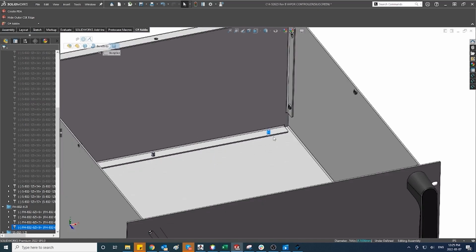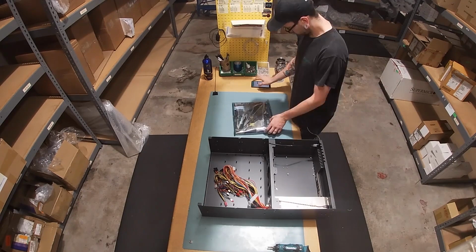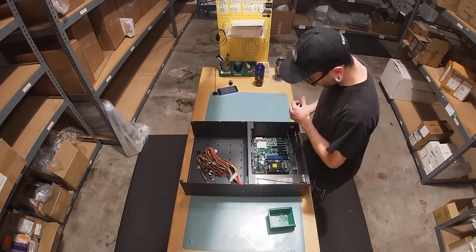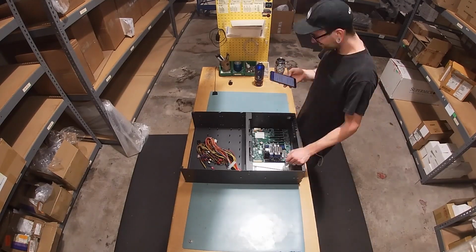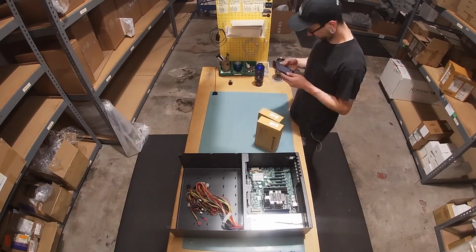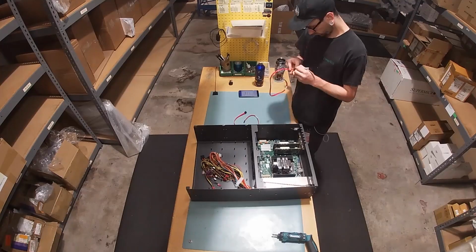When thinking about clearances, you always have to carefully consider where to place certain parts in your design. It is absolutely critical to make sure that there is sufficient space between your parts and components so that any manufacturing tolerances that could build up will not cause any type of interference in your part. When placing parts inside your assembly, you would typically use mates. That's because mates allow you to offset parts by a small amount. The idea is that they should never touch.